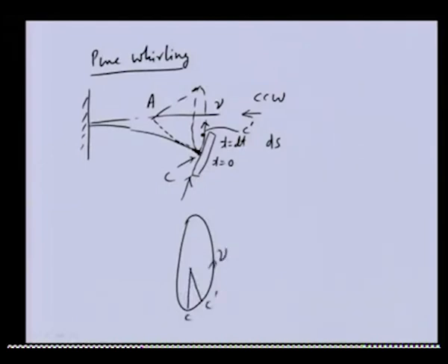Because the whirl frequency is nu, the angular velocity of the whirl is nu. Here we have the y displacement, and the tilt of the disc is, let us say, phi x, when we have the axis system with this as z and this as y. So tilting of the disc is given by phi x, and the translatory displacement of the disc is y.